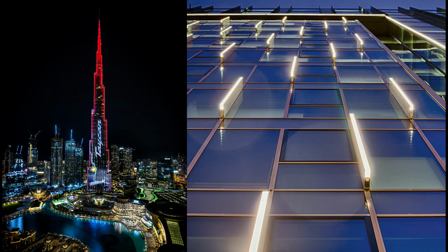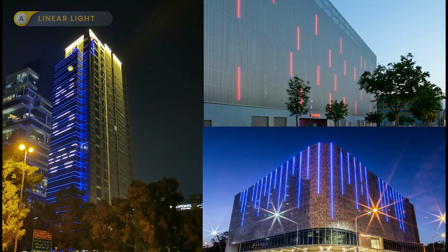Now technically, we are going to learn how to install the linear lights. Also we are going to see how to create the effect in Adobe Animate by using linear light, mainly for the dynamic, like for Burj Khalifa. Here, if you can see, this text can be played. This is dynamic linear lights. So we are going to see how to create that effect. And all the linear lights are DC 24 or 48 volt, so they need a driver. We are going to see how the driver needs to be connected and how far the driver can be kept. Because if we keep the driver too far, it will have a power drop. This is not AC power.